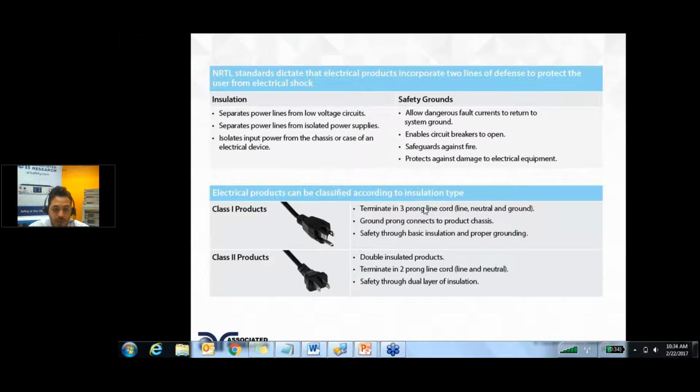I need to protect myself because someone has just shorted my output. When we see that OPP protection activated, that's one of the ways we say breakdown has occurred. So that's a little insight into how breakdown is defined.